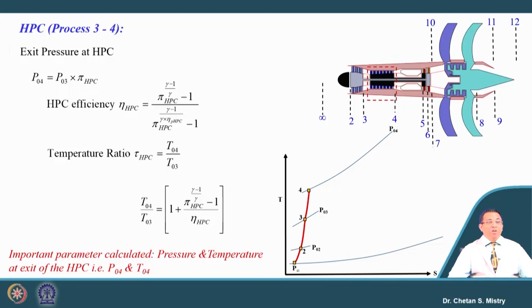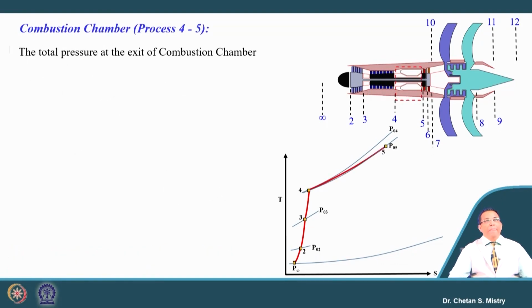So, you need to recall those terminologies and decide the pressure ratio and the efficiency that we need to assume. The assumption does not mean that you assume a compressor efficiency of 0.98, it should be a valid efficiency number and it should be achievable.